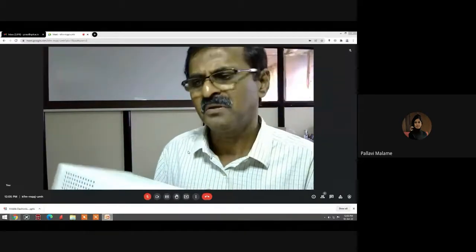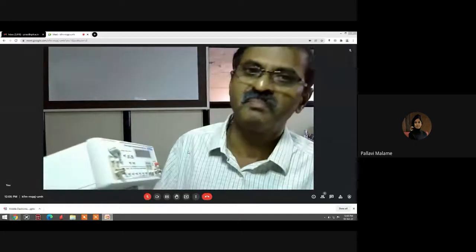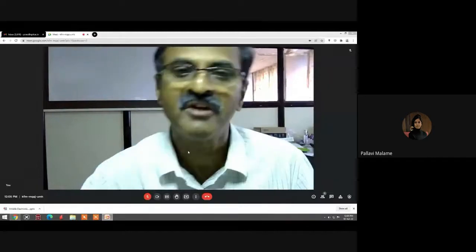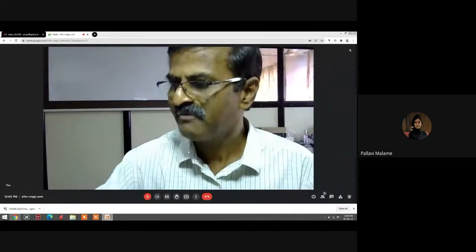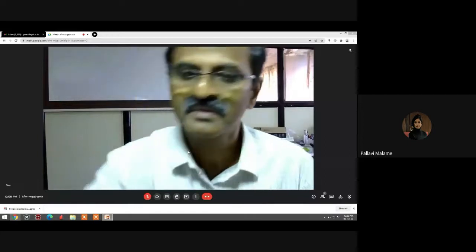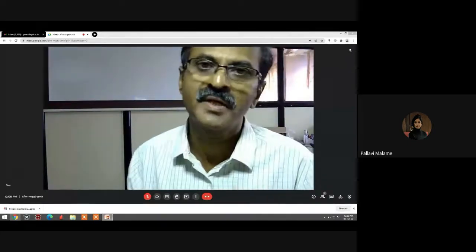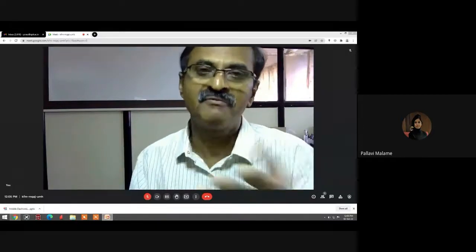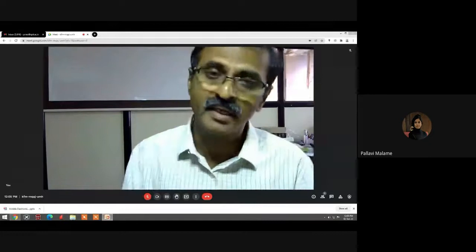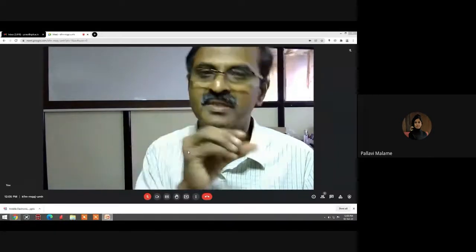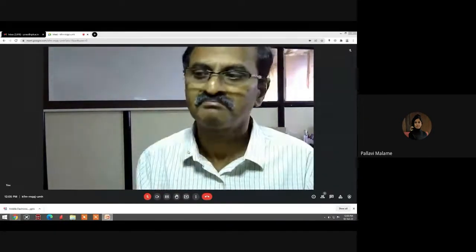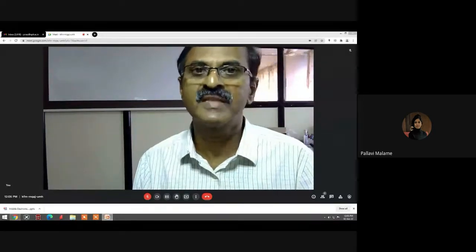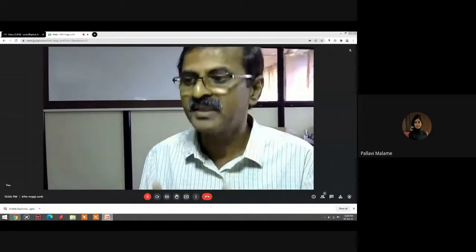All right. So this is again a most commonly used equipment in the laboratories, because you would like to have a reference waveform to be generated, so that whenever you design any circuit, you require input to the circuit, right? Some waveform you would like to give it, or some pulses you would like to give it, like for example, a counter you have in digital electronics, you would like to generate some pulses with a variable frequency. So that's why it's called a test equipment, because it will generate the reference signals.